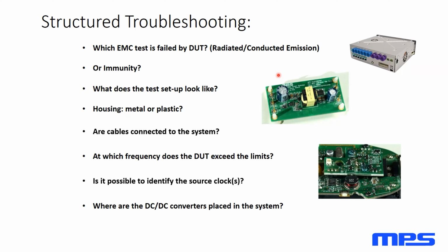Ideally, what we would like to do is, if this is the connector on this EVB, we'd like to have the DC to DC placed all the way over here. Obviously, physical limitations and design of the product may not allow for that, because we want to keep things away from noisy sources where we could have a path coupling back to the input, bypassing any type of filtering that we put on the board, and we'll take a look at that.